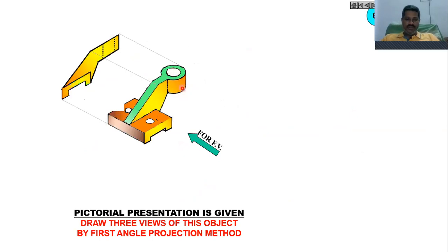Inside we have a hollowness with certain thickness. It's a hollow cylinder, so you will get two dotted lines like this. Then similarly, you have one more dotted line here that is not shown here, but of course we need to represent one more dotted line here. So exactly at this location, we need to get one dotted line. So this is the front view.